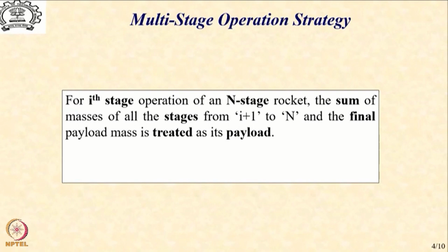And that becomes a kind of a payload for the ith stage, and that brings us to the definition of what we call the stage payload. So M0(i+1) becomes the payload for the ith stage, because that is the amount of mass that the ith stage will have to push along with its own mass, of course, and it's appropriate that we use the same interpretation.